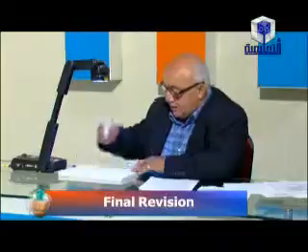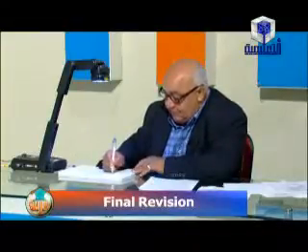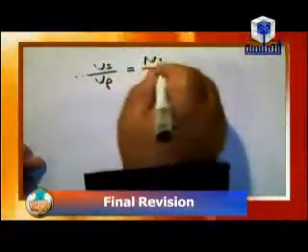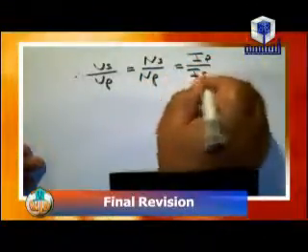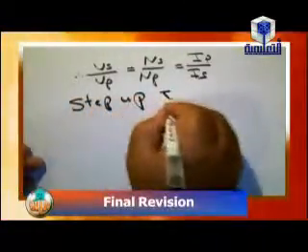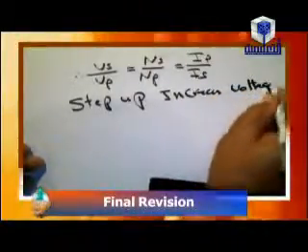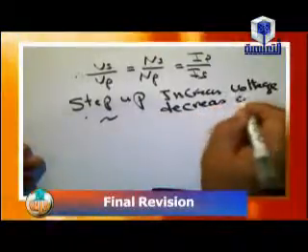I want to explain something about transformer. Transformer, we know that is used to step up or step down AC voltage. The rule is Vs over Vp equal Ns over Np equal Ip over Is. So step up increases voltage and decreases current.